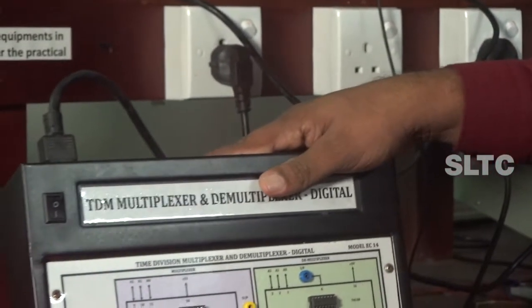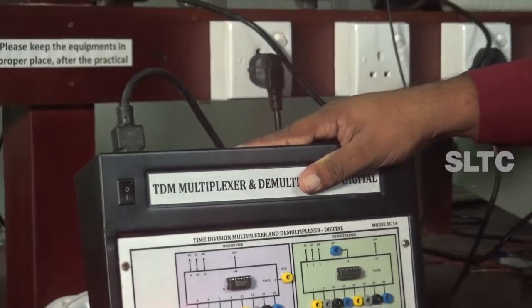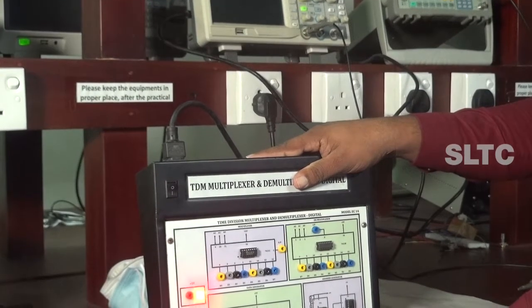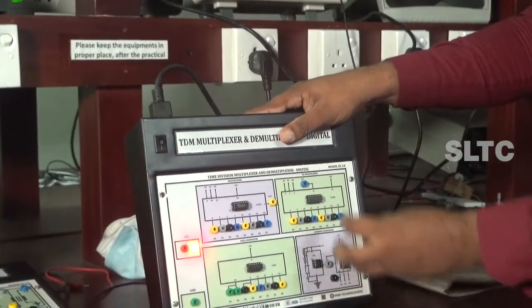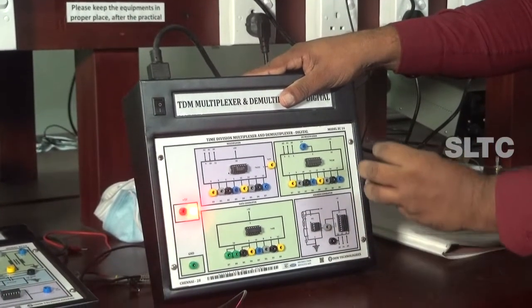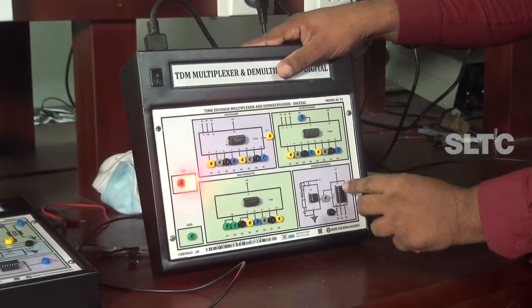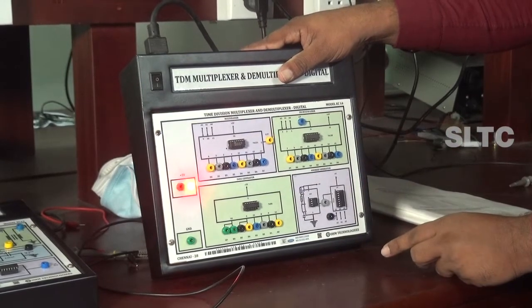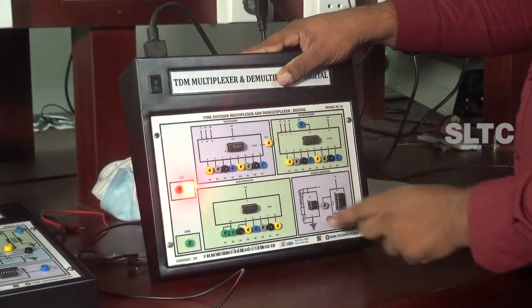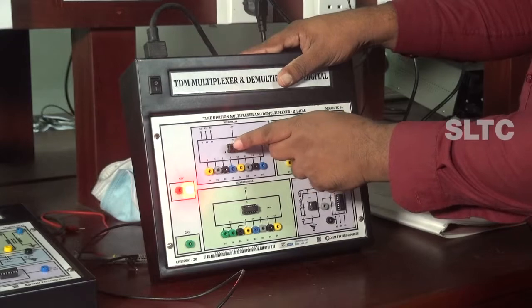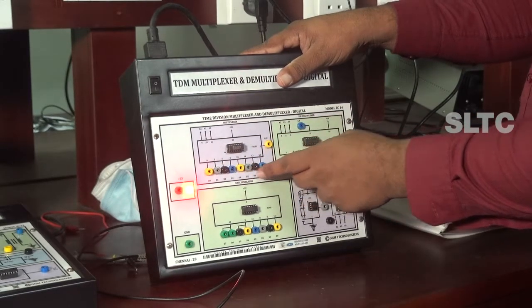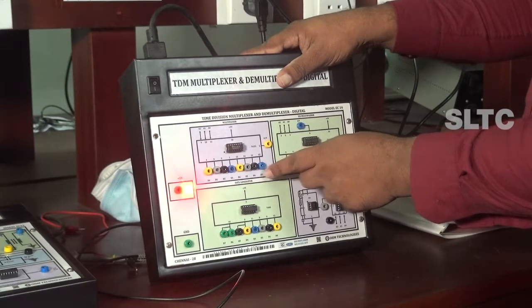You have an address bit generator and you have a clock there. This address generator will generate 8 addresses, and it instructs this multiplexer. It gives the information to this multiplexer about which output port should be selected.